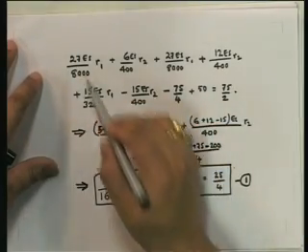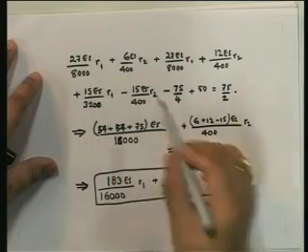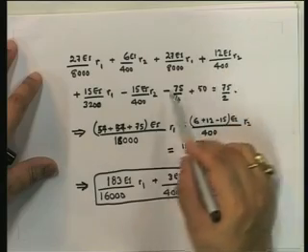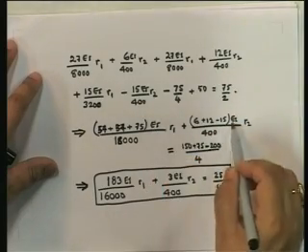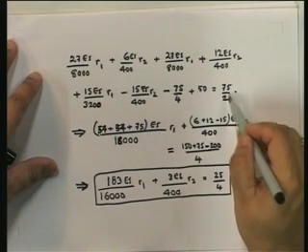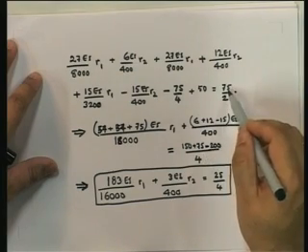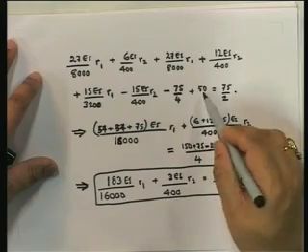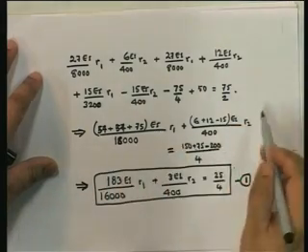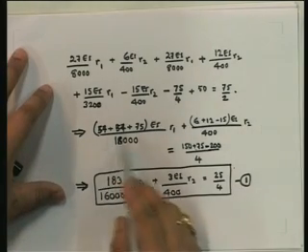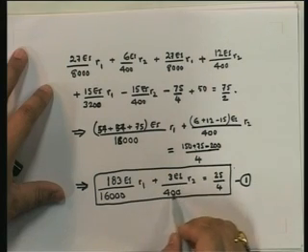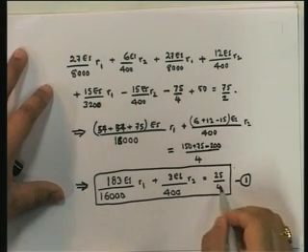If I put that, this becomes 54 plus 54 plus 75, that's R1, and then plus 6 plus 12 minus 15 upon 400 EI into R2 is equal to, now this is 75 by 2, so by 4 it will become 150, this minus comes here plus, and this 50 goes here, becomes minus 200. So substituting all of those, what I get is, this becomes 183 upon 16,000 EI R1 plus 3 EI upon 400 R2 is equal to 25 by 4.